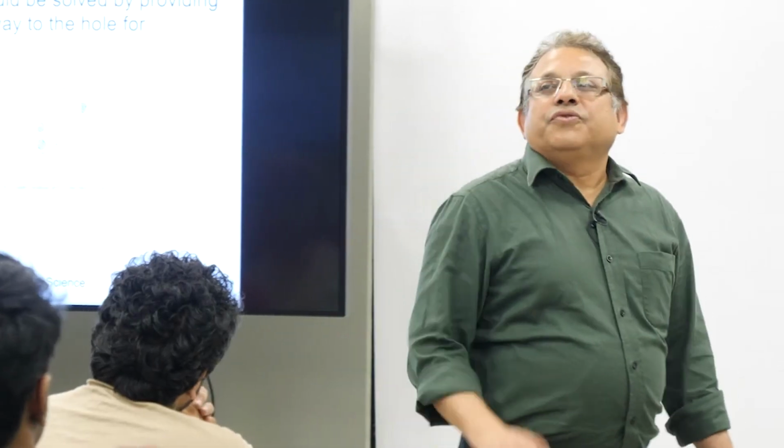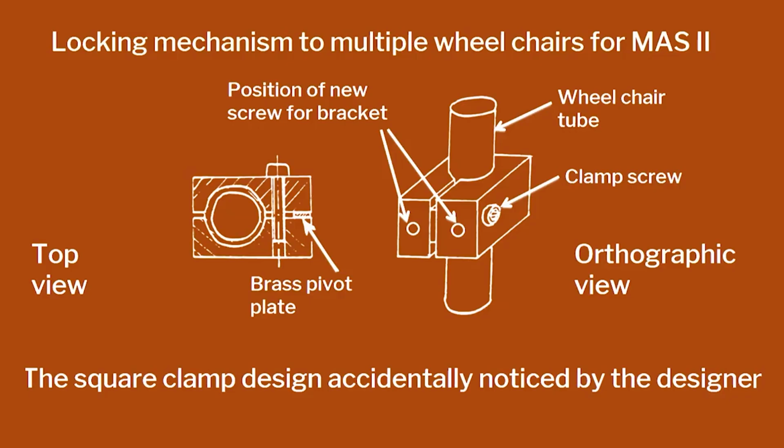But the bad news here is that this part is going to have a lot of bending, and that's not good. First of all, it's much harder for you to tighten it because you have to overcome that bending, and the screw has to go through a lot of stress, and that's bad news. So over a period of time, this is not going to remain a robust and reliable design.